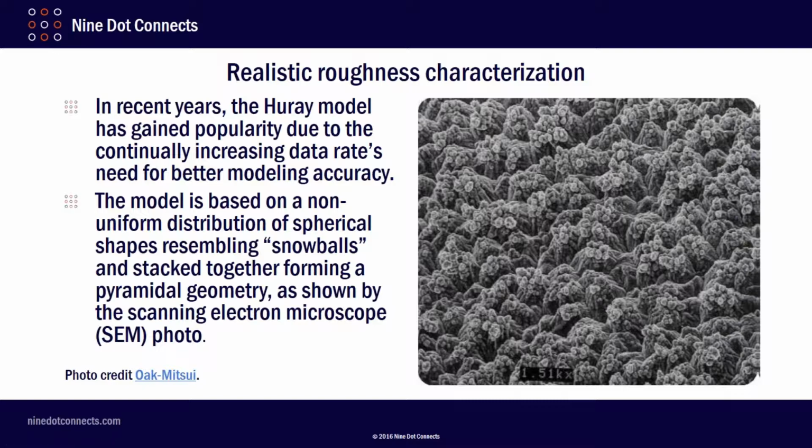This picture was created by a scanning electron microscope. So if you think about, okay, are the charges moving along this path perpendicular to what you see, these mountains and valleys? The electrons don't just ignore these. They actually go up and down, and they follow that surface. And that's why you end up creating extra losses the higher frequency you go.